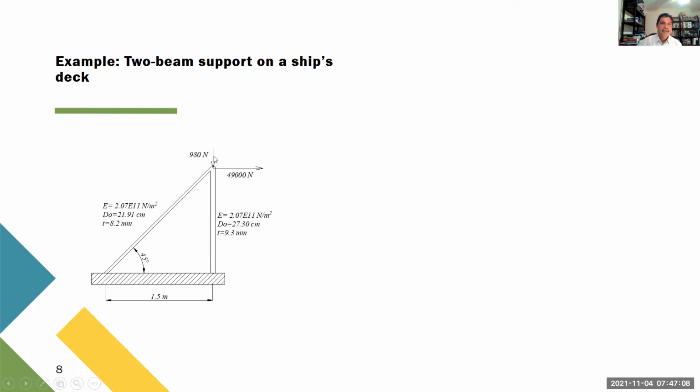And these two forces also will produce an axial force on this element. So in this case, we need to consider both effects, bending and also in plane force. So that's what we need, this element, which is beam and bar combined. And then we go.